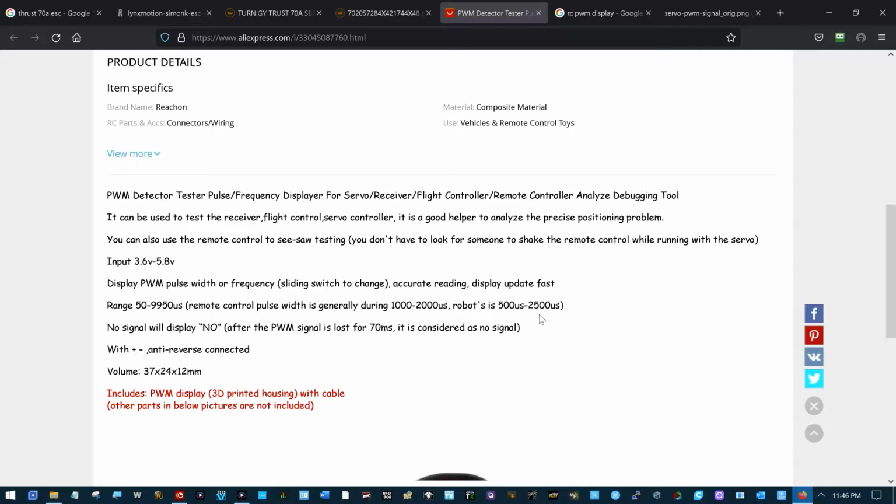That's kind of something that's gone the way of the dodo, because frequently now these new OpenTX radios, you can change your signal much more than you used to be able to. So you see, the smallest RC signal we're usually ever going to see is going to be somewhere around 500 or 550. In my humble opinion, and honestly, the largest one I think is going to be 2200.